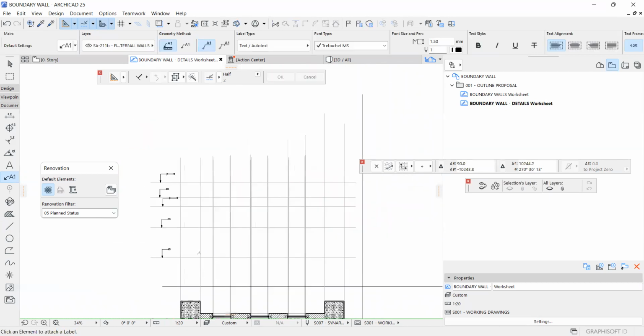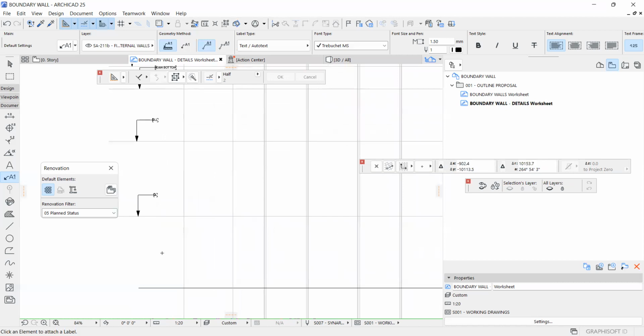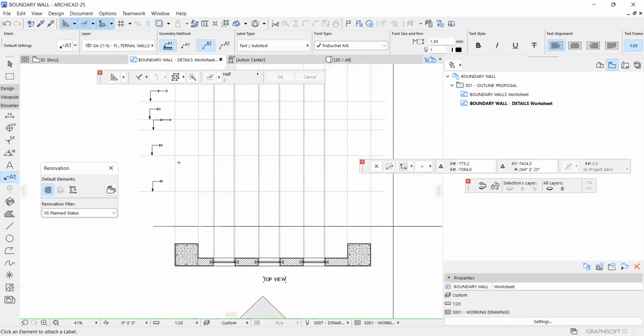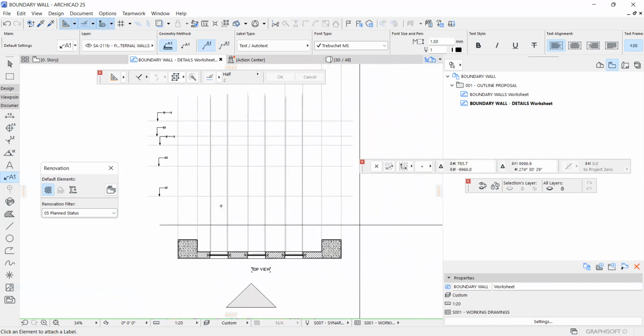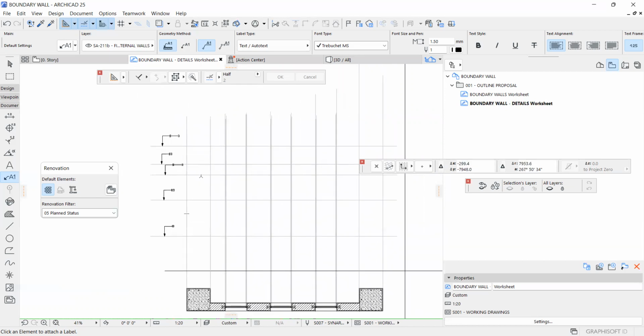So you'll notice that we have projected the positions of our windows, our walls, and our columns from plan. And then from our base, we have measured. So the front view always is a hybrid of the two. You must project and you must measure, okay? In our case, we have done that, so we can now start picking up the extent of our elements.